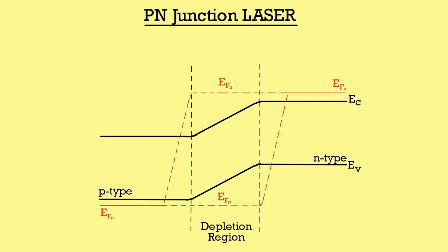By observing the Fermi energy level, you can see that the semiconductors used in the neutral n and p regions are degenerately doped. Therefore, the p-type and n-type regions are doped with such high concentration that the depletion region is not at all depleted of charge carriers. The name depletion region is merely for namesake.